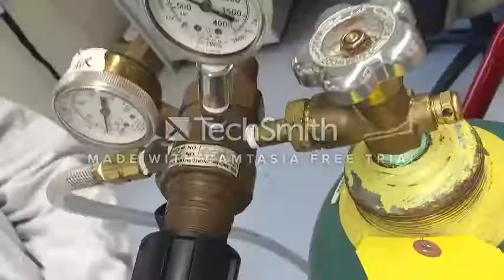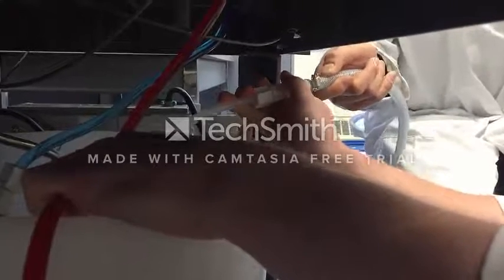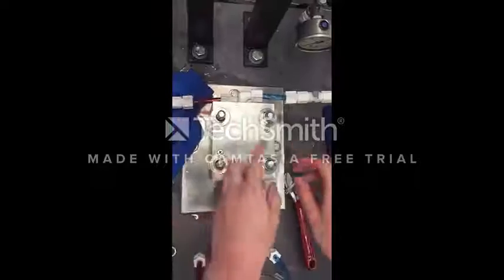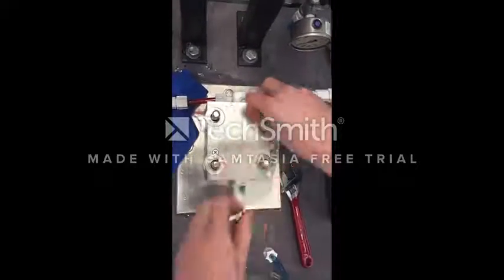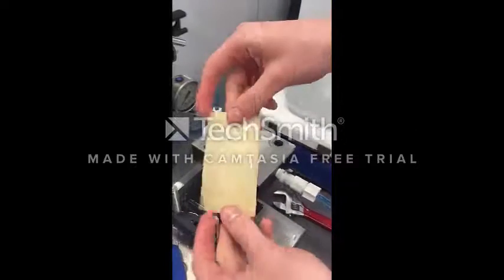The system must now be air purged. Set the air pressure to 200 psi. Connect the air hose to each of the discharge tubes. Purge until water is flushed through the system. After, open the cell compartment by loosening the bolts. Remove the membrane and inspect it for any tears or deformations.